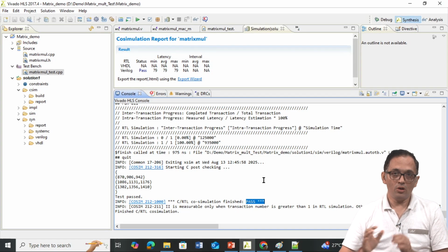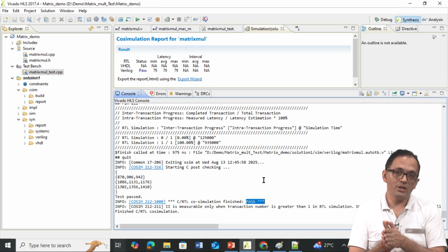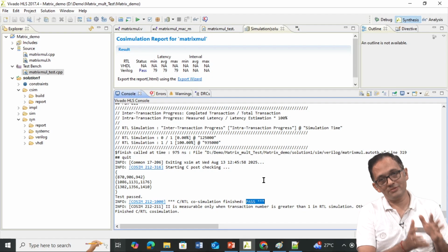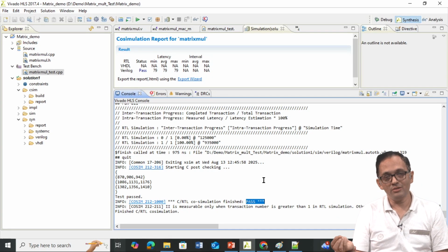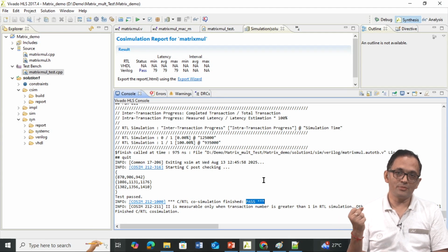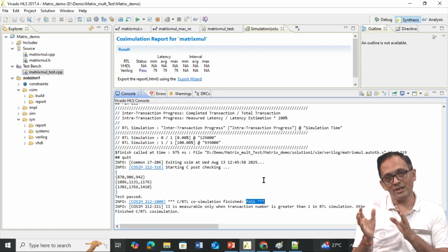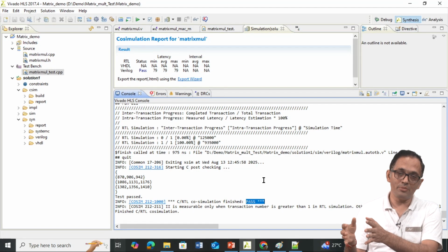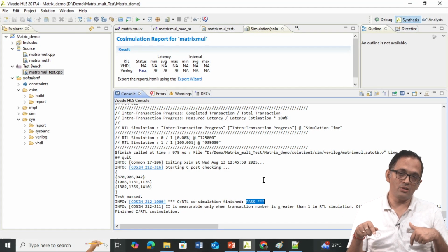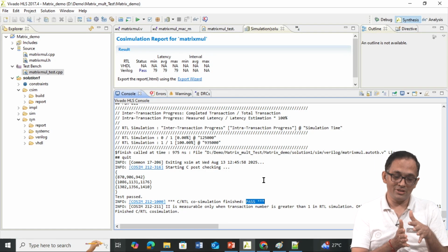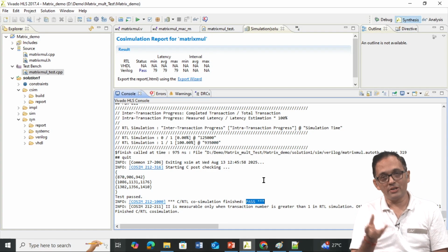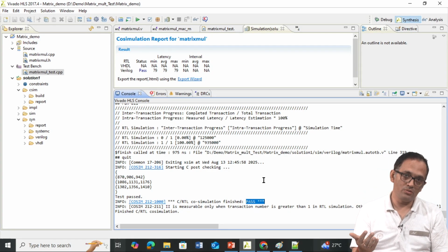So, that is all for the demo 1, where we have shown you how you create the test bench, how you do the C simulation, how you run the Vivado HLS to generate the Verilog, and how to understand the results in terms of the area, the resource, latency, initiation interval. We have also explained how you analyze your generated code, how the schedule happens, which operation is mapped to which Verilog code, right. All this correlation you can do through analysis, and then you should also see the generated Verilog. You have seen how the controller FSM is working and how the Verilog looks like, right.